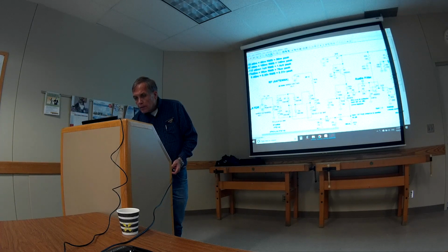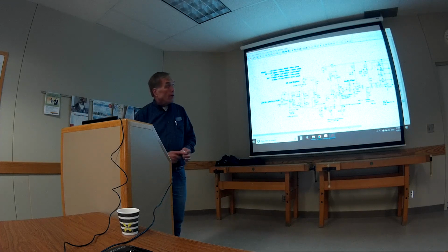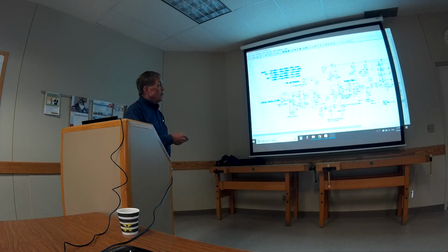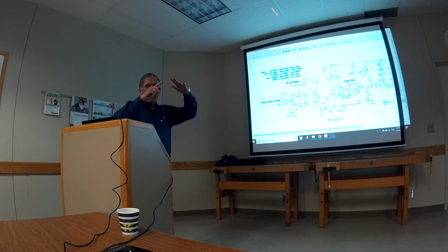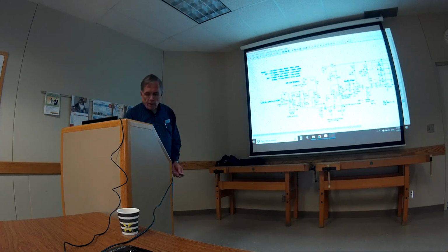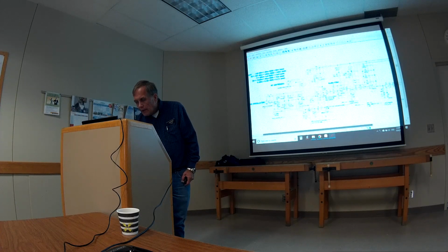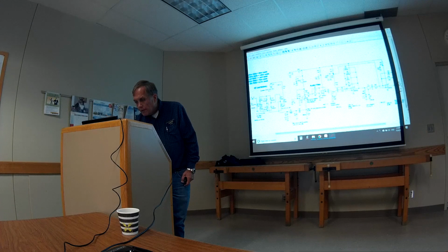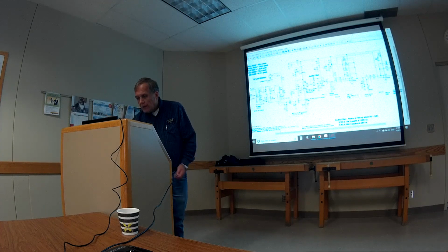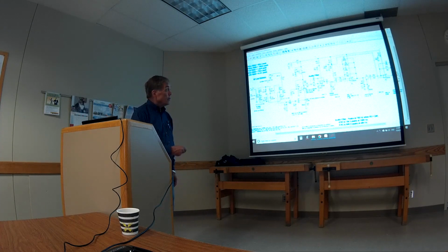I'm going to make this a little bit smaller so you can see. There's a simple audio filter. That's just going to peak it right at around 600. I've got notes down the corner about that too. But a nice little active audio filter. It says peaks at 700 when R3 is set and so on. If I wanted to change it to another peak value, I could change that little R3.